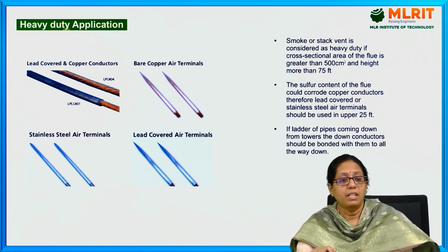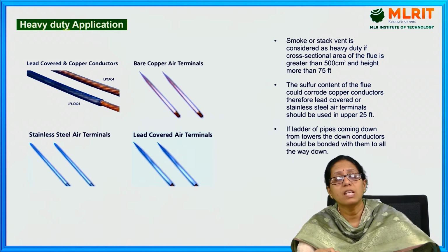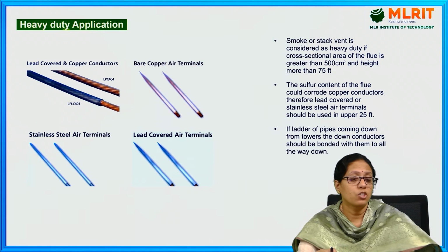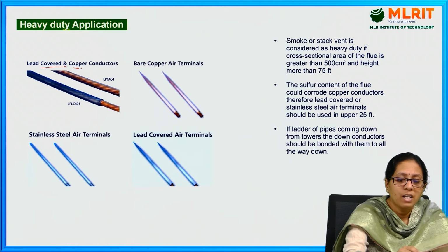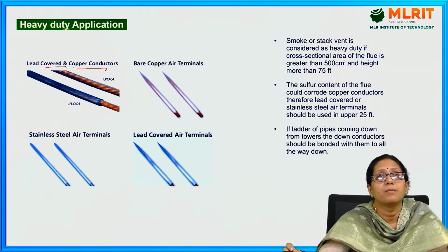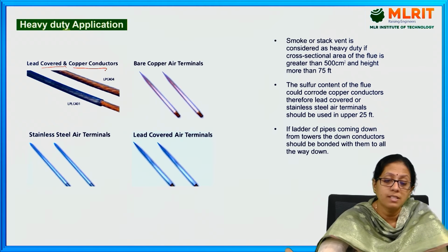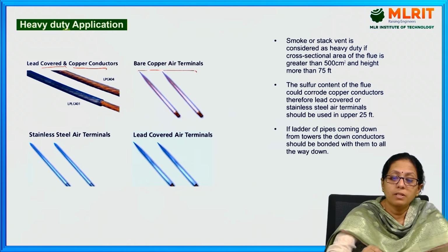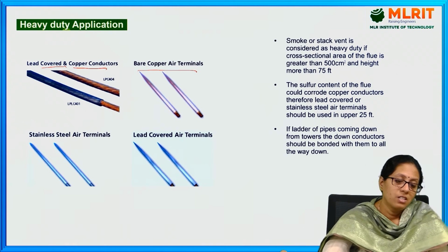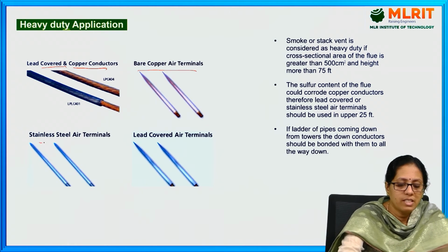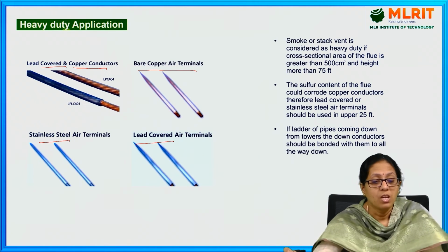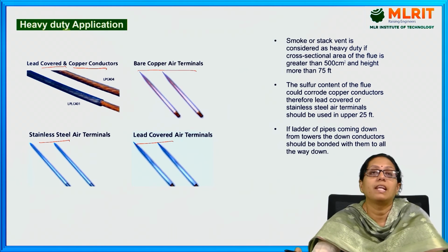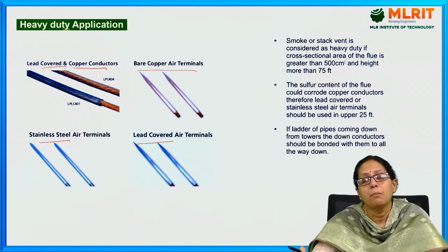Heavy duty applications. There are light duty applications as well as heavy duty applications of different cables. Here you can see lead covered copper conductors and bare copper air terminals. Here you are using stainless steel, and here again it is lead covered. So by using the lead or the stainless steel, the cables are being protected.